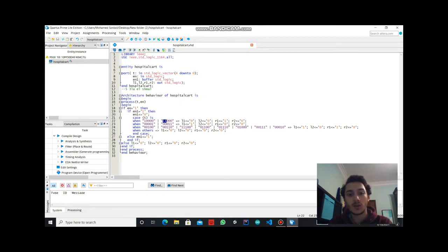So we set the outputs for our left motor to 0 to make it stop, and the output for our right motor, just the one concerned with moving forwards, to 1, to make the wheel go forward. So one wheel is stopping and the other is moving forwards, basically creating a left turn.